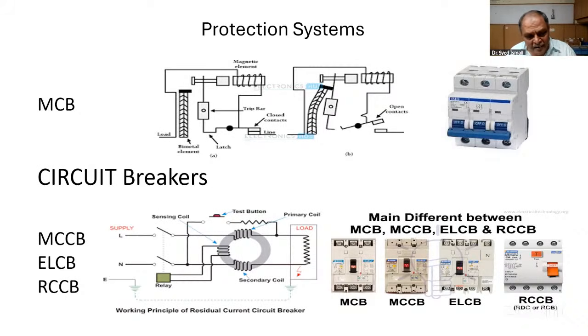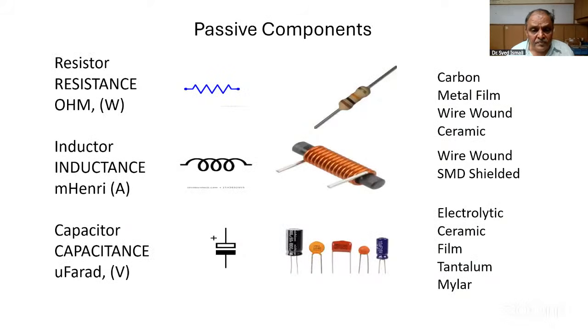RCCB is better in agriculture than ELCB. ELCB is used mainly in houses, old items. This is the old technique. RCCB is the latest, in the last 15, 20 years. It's slightly more expensive than ELCB. Earth leakage or residual current, these two are the difference. For those who look at the details, I think RCCB is very safe for you. Remember that much, note it down.